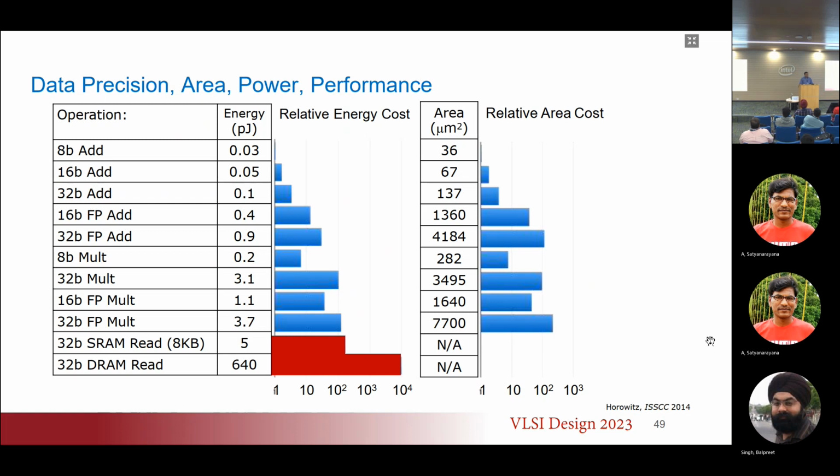So if you want to reduce the number of DRAM fetches or DRAM stores, then we have to organize the computation in a way which is going to be called stationary. Just keyword is stationary. We fetch the data, and it's sitting in my cache, and I want to do as much as I can with the data before I send it back to the memory.